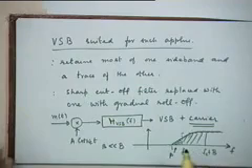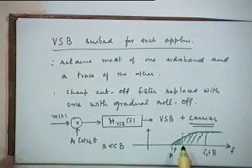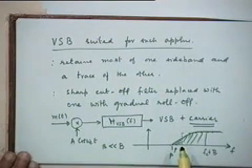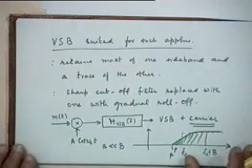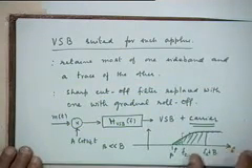The two requirements: one is we want to save the bandwidth, which we have done, not by the whole amount of B, but more or less by a fairly big amount. For example, for the TV signals, this could be, let's say, 500 kilohertz, as compared to 4.5 megahertz. This is still a good saving, right? And so on and so forth.